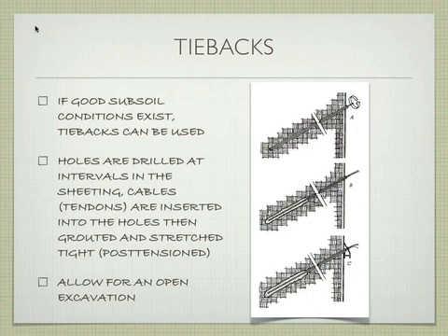Certainly, if your neighbor has this, and this goes into your lot, and then you decide you want to dig down and put it into their lot, which is already an excavation, that's a big problem. So at that stage of the game, you'd have to reconsider how this building is going to work in the first place, because those tiebacks are no longer going to work. This middle wall between your two buildings would become a joint wall, or you'd have to build two separate walls or something. So there are tricks to it.